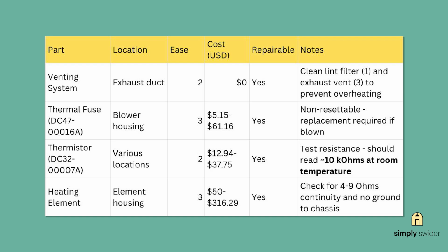Here's the thing though, the fuse is usually just a symptom, not the actual problem. 9 times out of 10, it blew because of restricted airflow from a clogged vent or lint filter. So clean everything thoroughly before you replace that fuse, or you'll just blow the new one too.